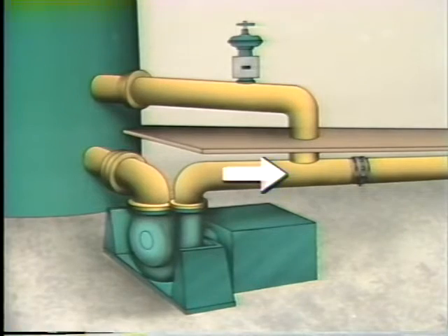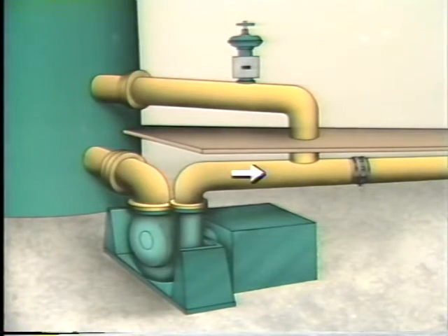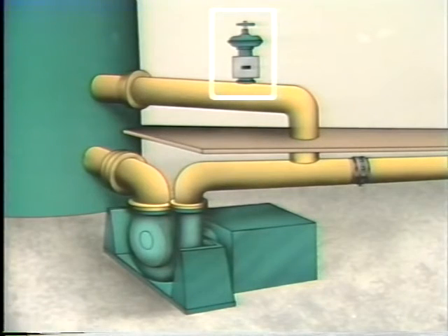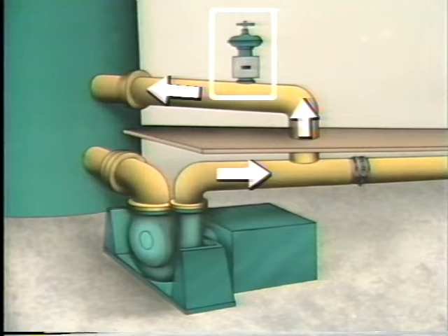So when the demand for condensate decreases, causing the flow to drop below the given value or set point, a valve is opened in this pipe to recirculate the condensate back to the tank. Recirculating condensate to the tank allows condensate to continue to flow through the pump at some value above set point and prevents the pump from overheating.